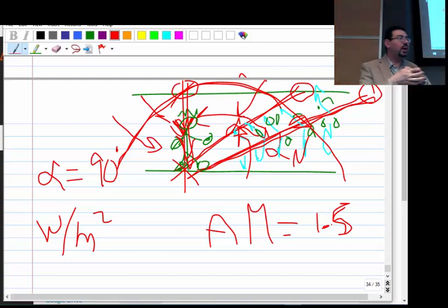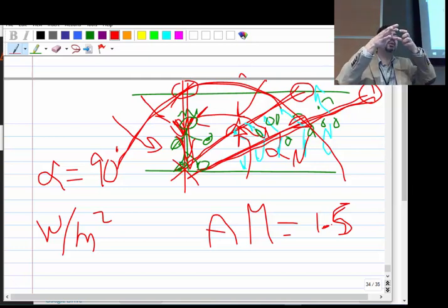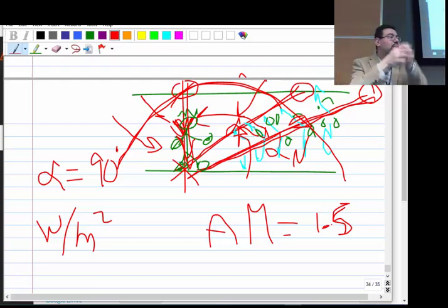Some are called concentrating solar cells. Rather than having a big blue thing, they have a tiny blue thing, but it's very expensive because it has multiple junctions, and they have a lens on top of it that focuses all that radiation onto that tiny expensive cell. So they care whether I can direct that toward me or whether it's coming with an angle.